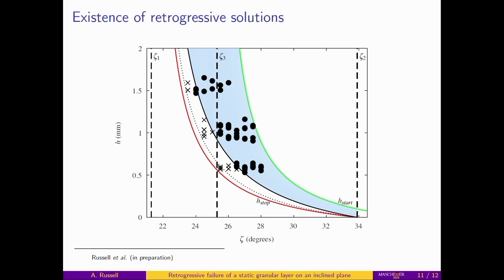It's probably within the experimental error, because the inclinometer that we have has a precision of about 0.1, but in reality it's probably larger than that. So it's within experimental error, I'd say, because that one was probably just to the left and that one was just to the right. So there's going to be an error in the thickness we can measure with our laser and an error in the actual angle of the slope from the inclinometer.